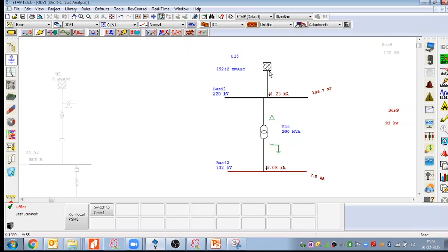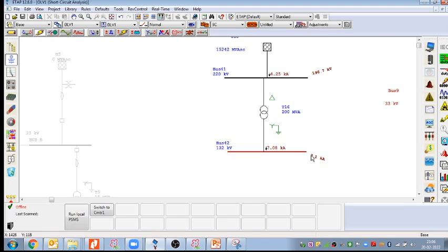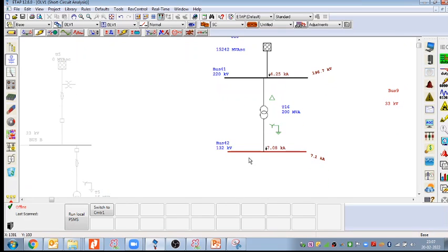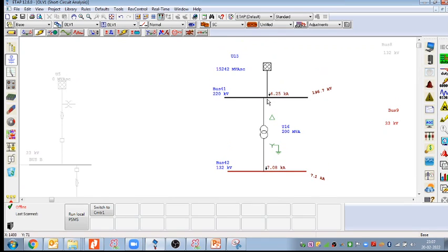This grid will increase in 30 years. In the next 30 years, the load we have connected, that we have not indicated at present, is also going to increase. So we are considering not only the present grid rating. Grid means the combination of thousands of generators, right? The number of generators will increase, and load will grow: the industrial load, the commercial load, the residential load, all the load will increase. So that load will contribute to the fault, and that grid will contribute to the fault.